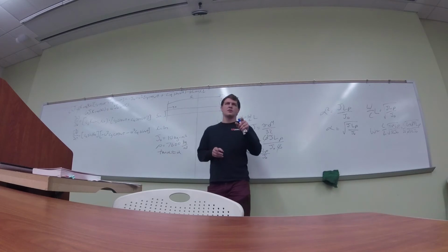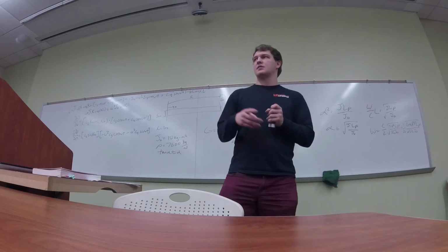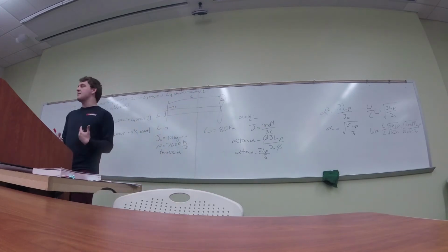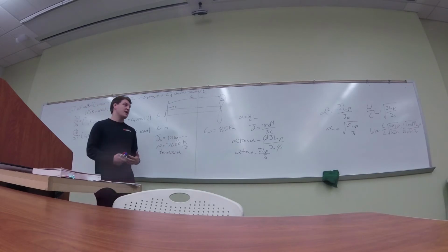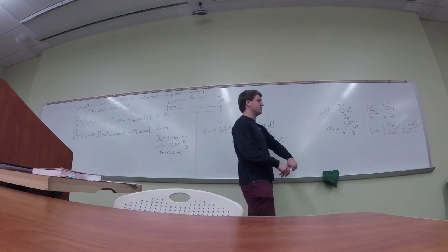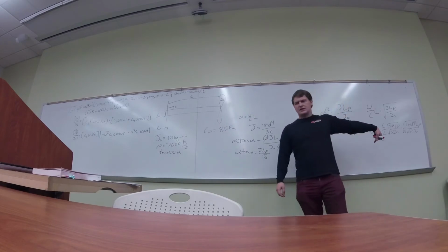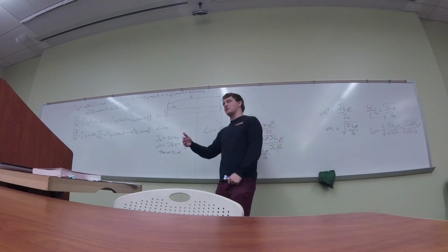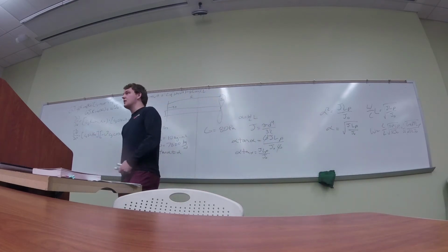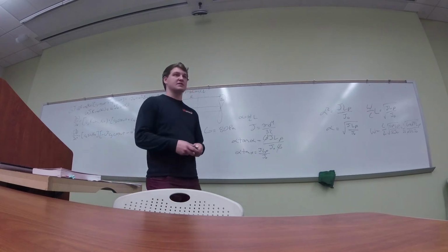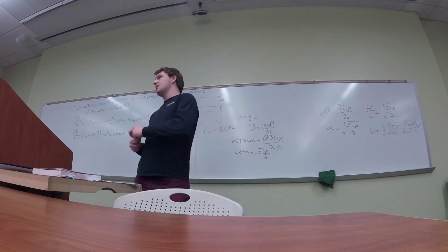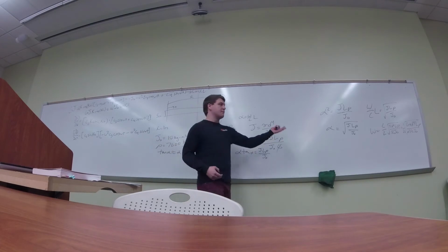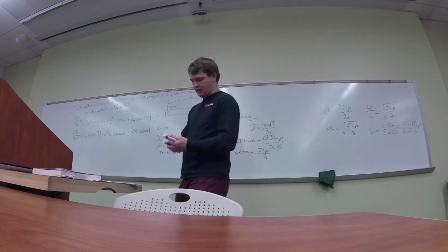Did I see another hand, or was that kind of answered? Yes. So this is the first natural frequency? Yes, and in the problem he says, look for the fundamental natural frequency. If you didn't want to look for the fundamental natural frequency, you would solve for this omega, and then you're going to have some sort of n over here, so that you'll have your second natural frequency, your third, fourth and fifth, because you're going to resonate at those different natural frequencies. But we're just looking for this initial one.